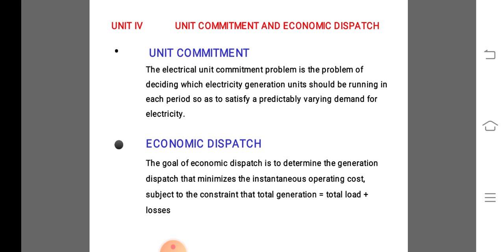During operation of the plant, a generator may be in one of the following states: base supply without regulation, where the output is constant; base supply with regulation, where output power is regulated based on system load; automatic non-economic regulation, where the output level changes around a base setting as the area control error changes; and finally automatic economic regulation, where the output level is adjusted with the area load and area control error while tracking an economic setting. Regardless of the unit's operating state, it has a contribution to the economic operation.